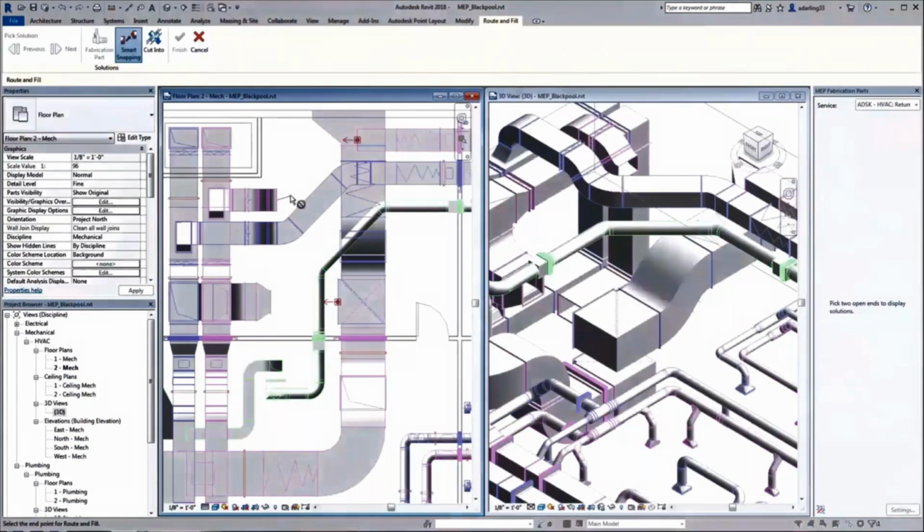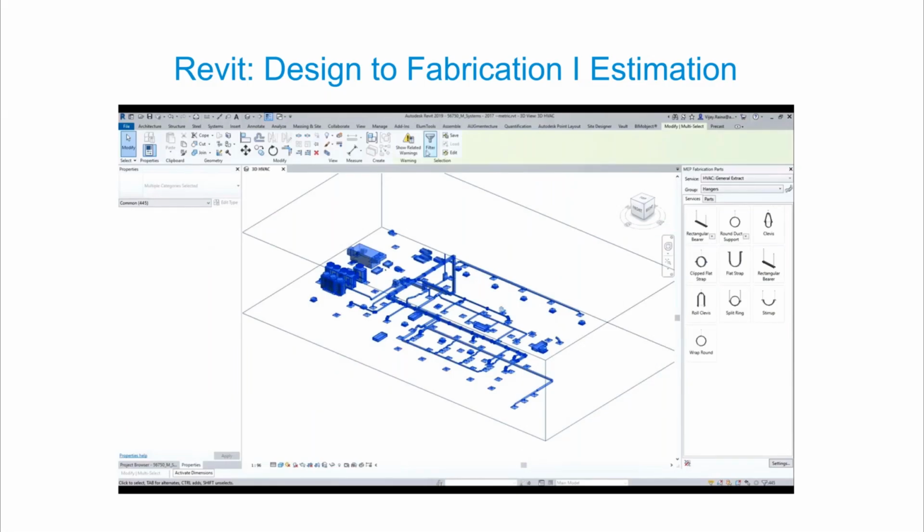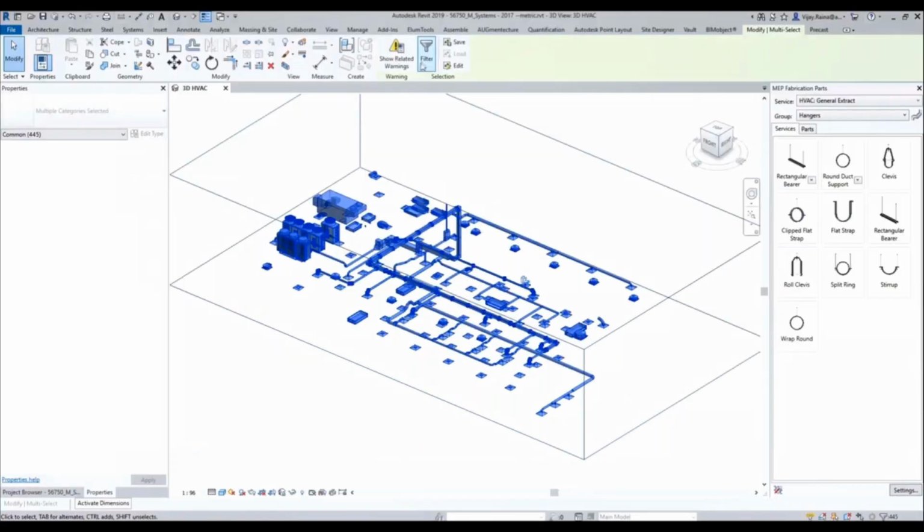And for the estimation, once everything is ready, I want to push this complete model for the estimation purpose. You want to come up with a complete report summary. What is the estimation of the complete ductwork? If you want to do some sort of costing analysis and variation analysis, I can select all these complete services, and with this simple option you can export this complete ductwork as a MAG file, which is a job file. Okay, .mag. So I can export it as a MAG file.